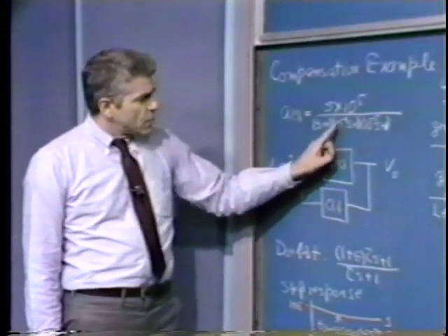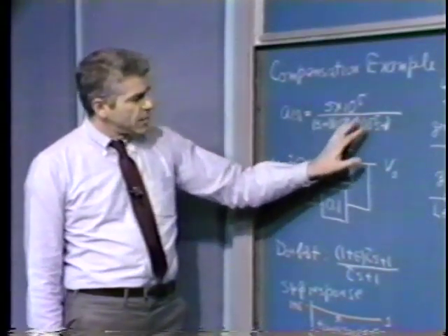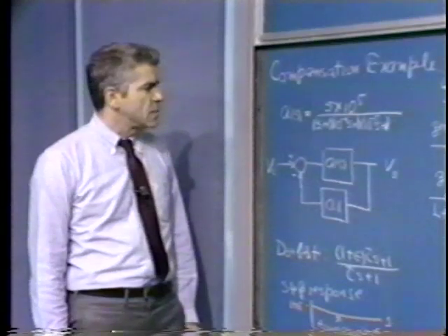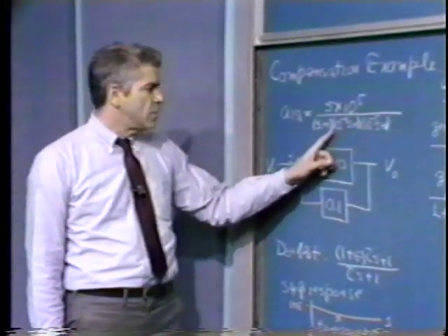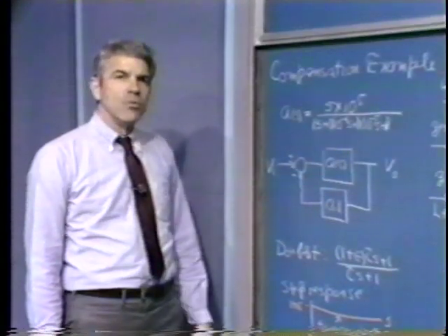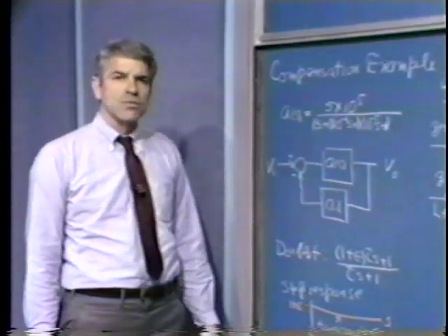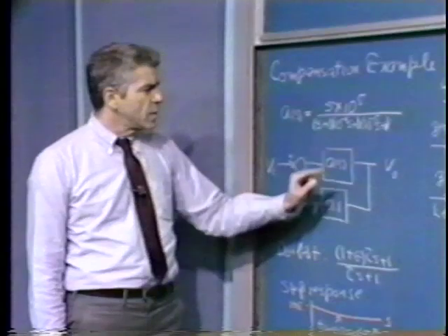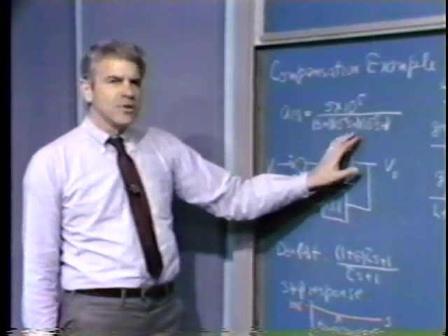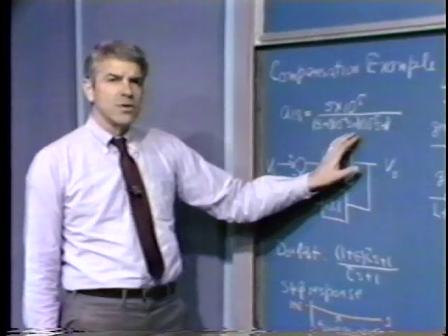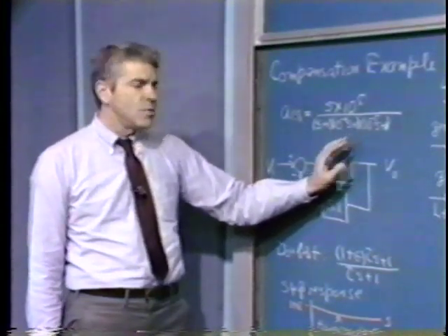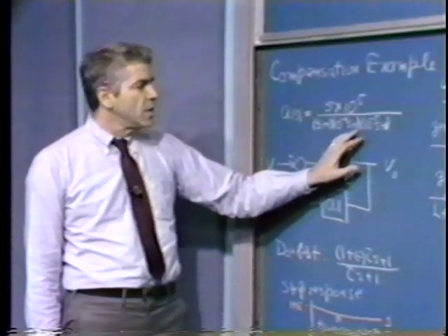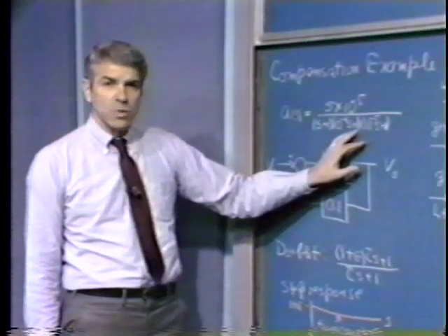The form where we have the high frequency additional poles coming in at somewhere on the order of 10 to the 4th radians per second is unrealistically slow for modern operational amplifiers. A more realistic value might be something on the order of 10 to the 7th radians per second for many of the common integrated circuit operational amplifiers. The reason we do it this way is that we make sort of a pseudo operational amplifier using several others so that we can control the transfer function very well. And in order to be able to do that, we'd like to have the important dynamics of our pseudo amplifier occur at frequencies well below the ultimate limitations of the components we use to build the system.